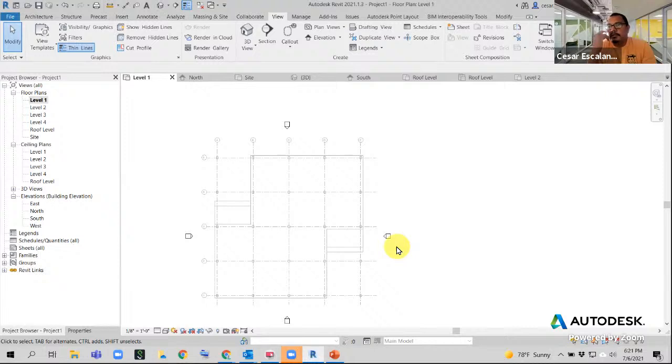accordingly in your project. So let's create a view template. And this is fundamental, guys. View templates is the functionality in Revit that controls how your construction documents, your final sheets are going to look like. And it captures the way your company displays the scope of work that is associated with your contract.